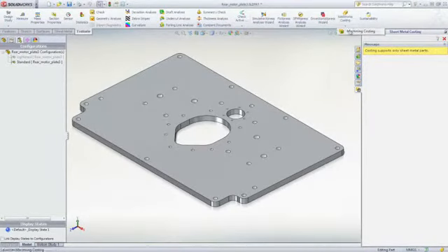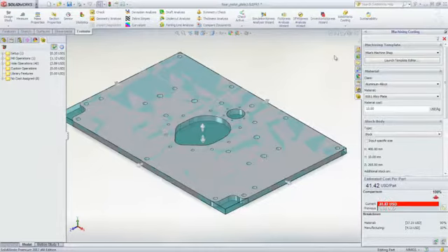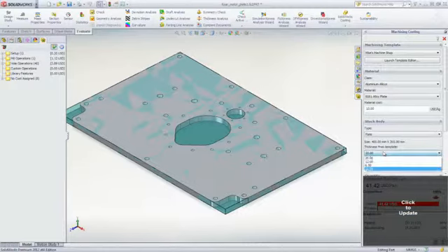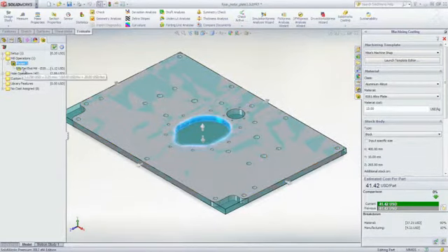Costing automatically switches to the machined template and calculates the cost. You have the ability to choose if the part will be machined from a solid block of material or from stock plate material. Part features are sorted into cutting, milling, and hole operations. Tooltips explain the calculations used for estimating costs and time.